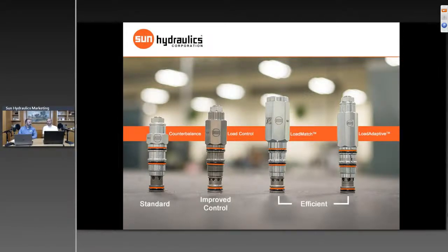The standard capacity is going to be the highest rated capacity for that. And if we're talking about Series 1, the T11, that's going to be 15 gallons per minute. There will also be the semi-restrictive, restrictive, and ultra-restrictive, which then still fit the same cavity, but cut down the capacity to lower values. The difference internally is we have smaller milling, smaller connecting paths through the valve while you're doing that modulating, while you're actually doing the motion control, that physically make the valve more restrictive. It causes additional pressure drop to go through it.